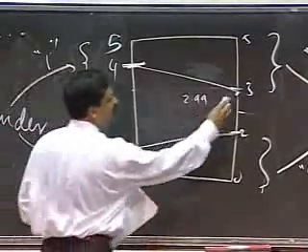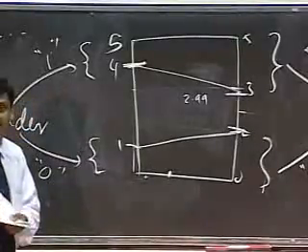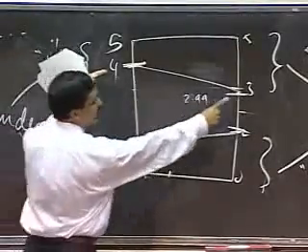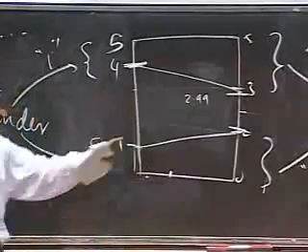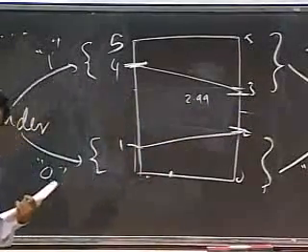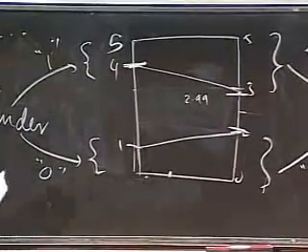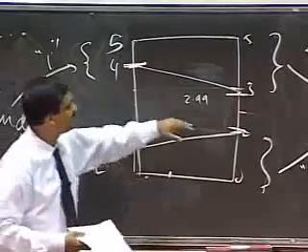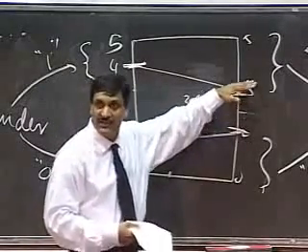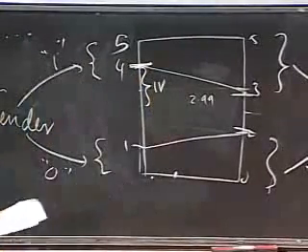Notice that the lowest value that the receiver can receive is 3 volts. So if I sent a 4 over a long cable to you, the value can be beaten up by noise to such an extent that you may begin receiving 3s, but nothing lower than a 3. So this is a noise margin, 1 volt.